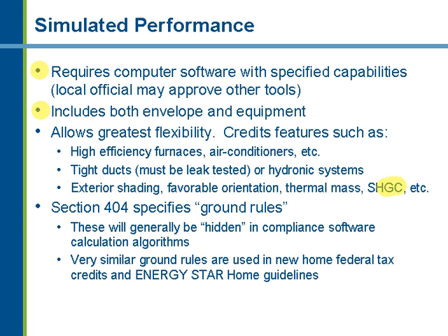It also has an approach in there that will allow you to take credit for specifically tested type ductwork. If you have done an extra good job of sealing your ducts and you have a test to prove it, you can take credit for that in the performance path.